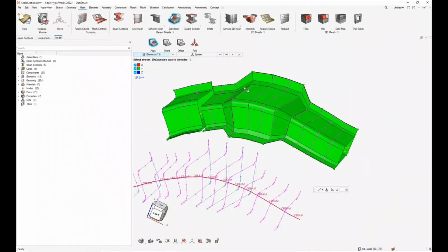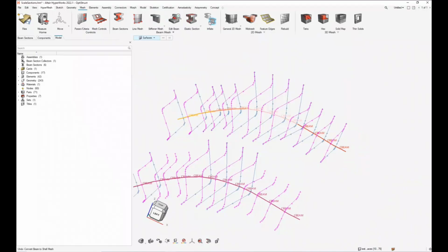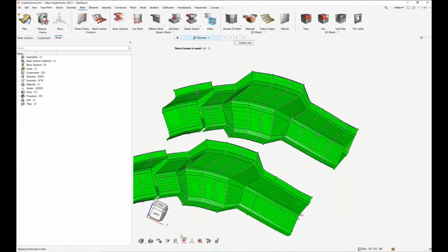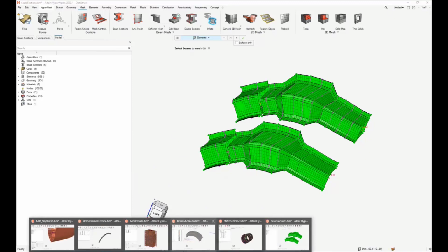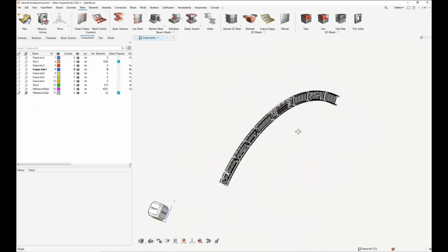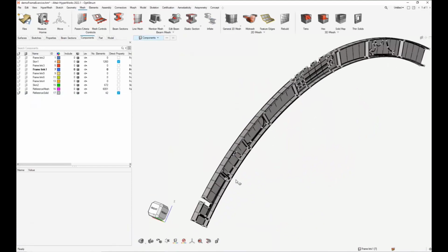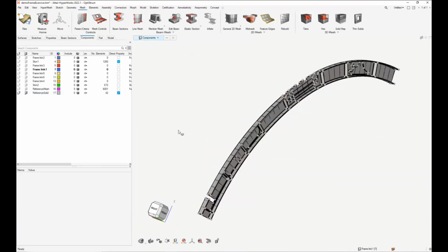and shell mesh. So if we again do a Control Z and do a Control A, we'll get directly the shell mesh. So I can go quickly through this one now to show the example I was mentioning before. If I take my elements, I do Control A and suppress each and every element. So I have here a solid.